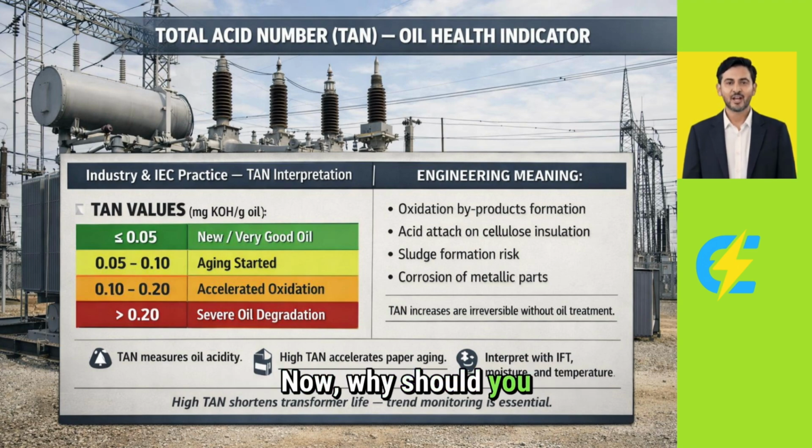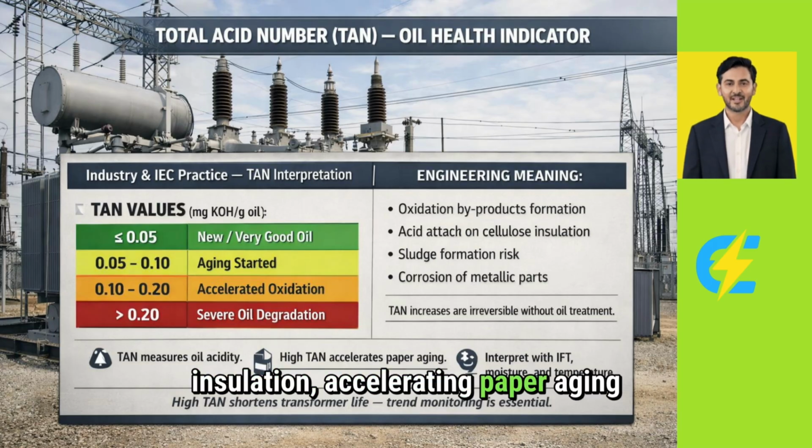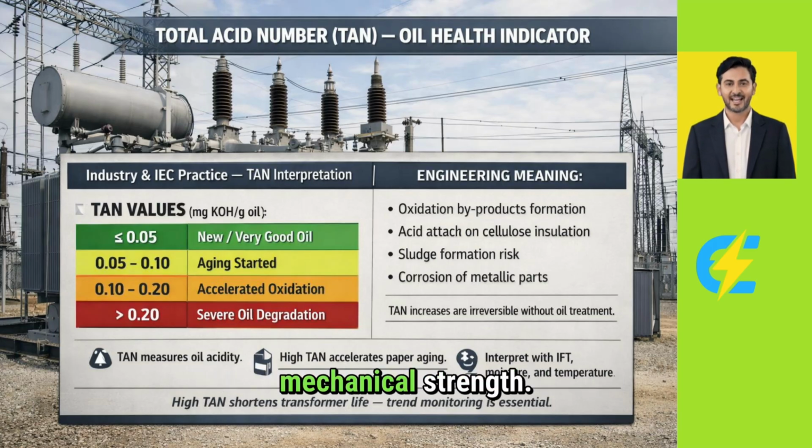Now, why should you care about rising TAN? These acids do not trip protection, but they destroy oil quality silently. High TAN leads to sludge formation, which blocks cooling ducts and reduces heat transfer efficiency. The acids attack cellulose insulation, accelerating paper aging and reducing the transformer's mechanical strength. They also cause corrosion of metallic parts, particularly copper windings and steel tank walls. This is why TAN is considered a root cause parameter, not a symptom. It's the beginning of a cascade that ends in transformer failure.